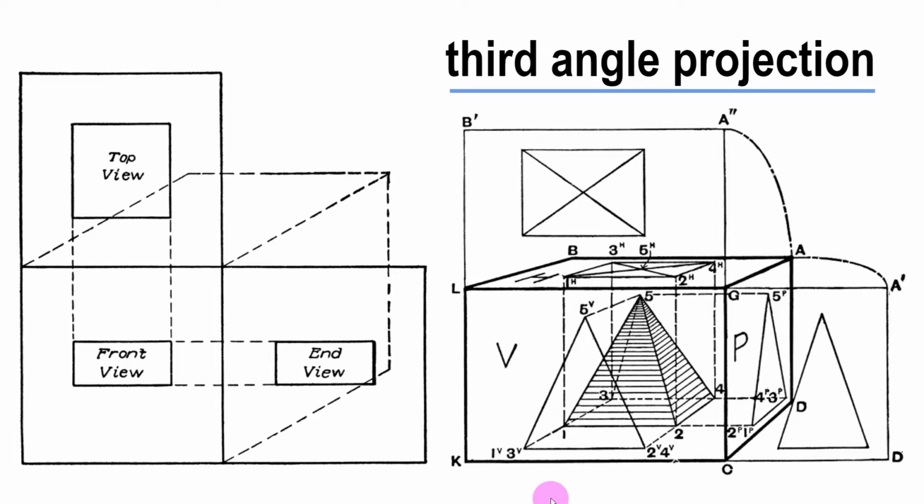This isn't something I want you to stress too much over, but again, this is related more towards industrial design. So one thing to keep in mind is in America, we use something called third angle projection, in which we have our front view with our top view aligned above that, and then usually the right side.